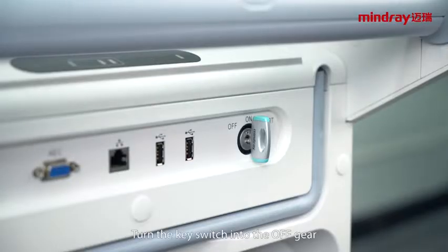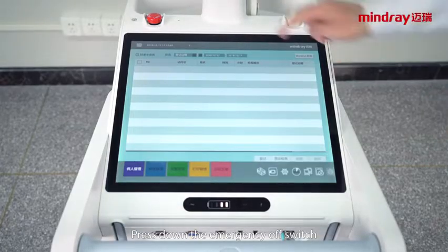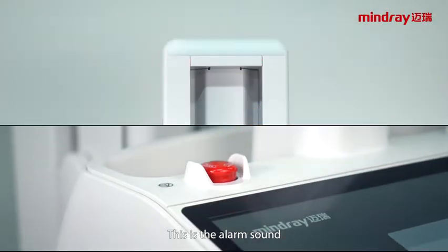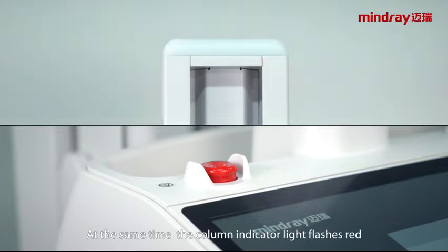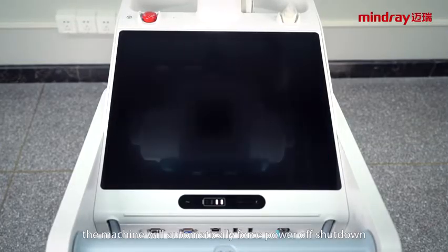Turn the key switch into the off gear. Press down the emergency off switch. This is the alarm sound. At the same time, the color indicator light flashes red. This is a normal phenomenon and don't worry about it. Wait for about 10 seconds. The machine will automatically force power off and shut down.